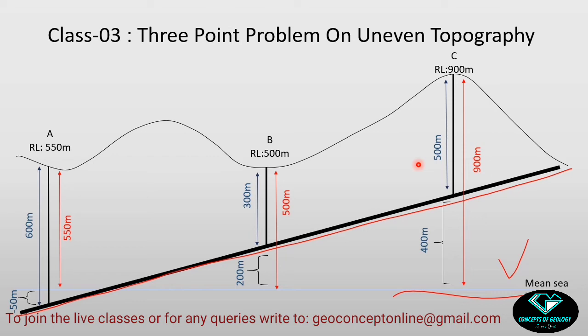So what we should do is convert the depth data into some kind of value which will not be variable. So instead of measuring the depth, we can measure this elevation. This elevation will not be variable because it is measured with respect to the mean sea level, and the mean sea level is a static factor.